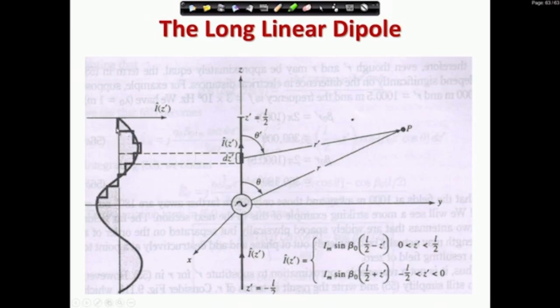So, basically this whole long dipole I can break into current elements distributed throughout its length, and each current element will have a current value that I know from the assumed current distribution. Then I will find the field at P, take a superposition of those fields and find the total. To do that we need to modify some of our terminology.